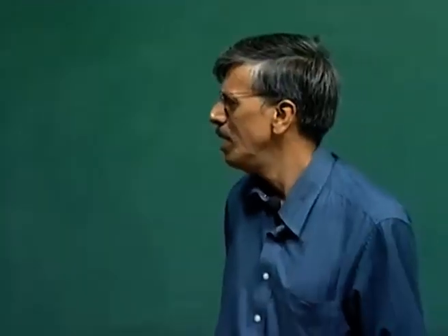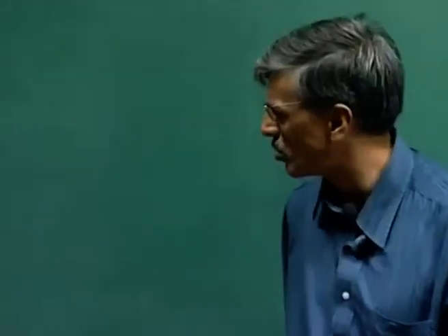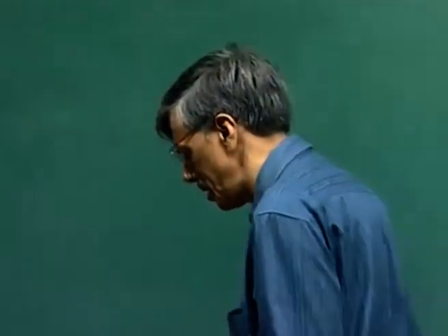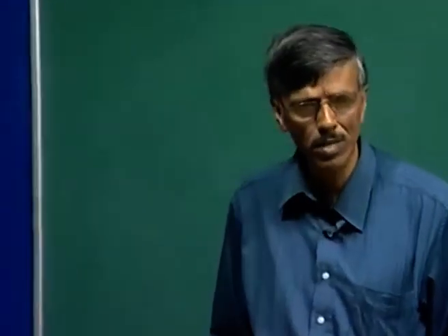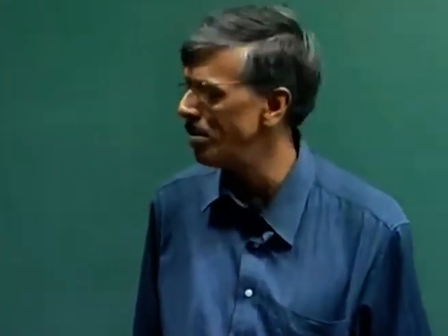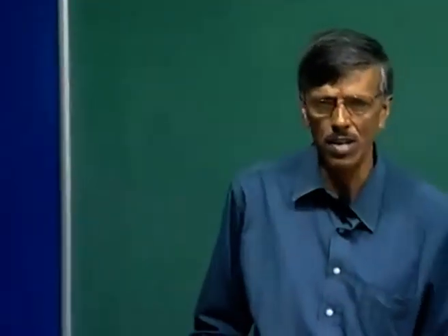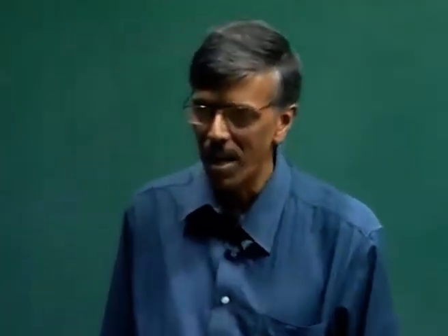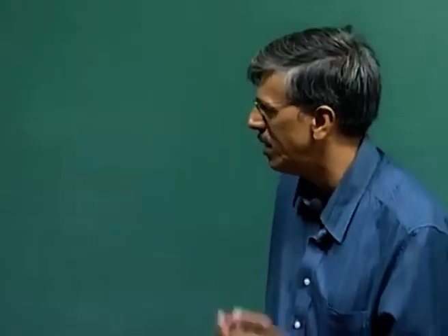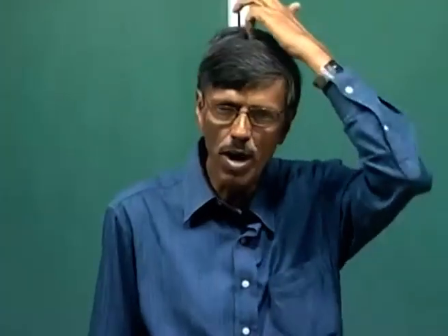Now, you see, we have talked about the historic development of the subject per se, that while the German school was very vehement in their pronouncement that there is an instability problem, experimentally it had never been obtained. And one of the experiments was done by G.I. Taylor, and what he did was he took a flat plate boundary layer, and in the middle of the tunnel put in a kind of vibrating bump, and that bump was oscillating at a fixed frequency, and he could not detect any wave solution, and he pronounced that this theory would not be correct.